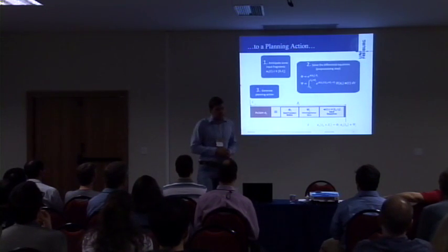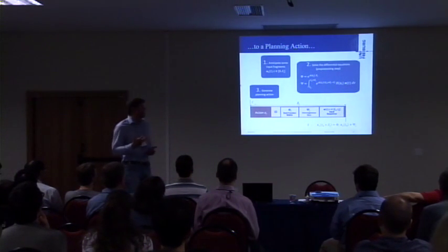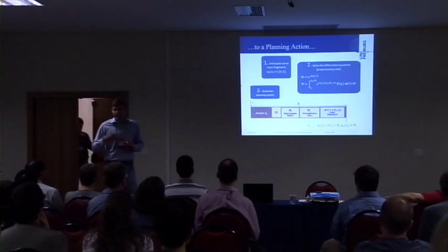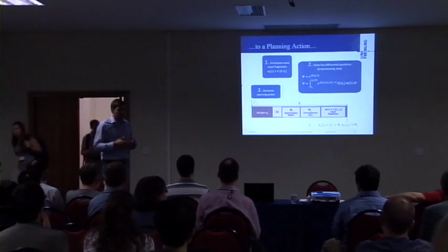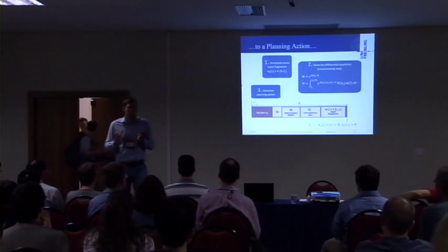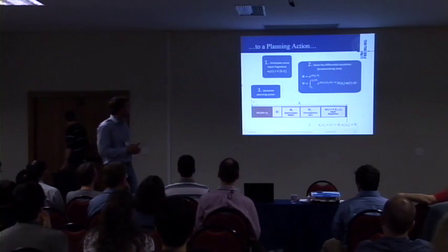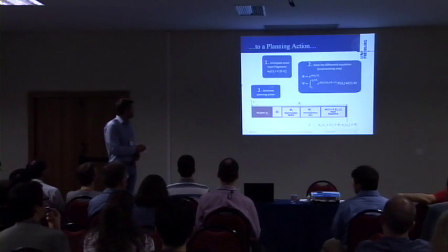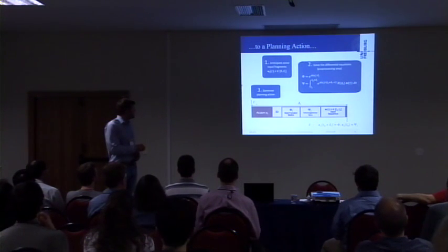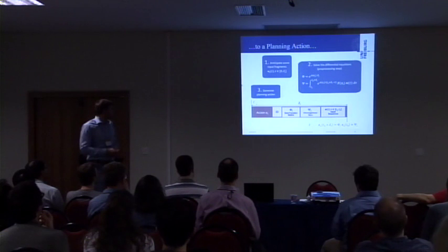Therefore, we basically have a three-step process. First of all, we anticipate some input fragments, for instance, the actuation of a thruster or a whole braking maneuver, or something that we can imagine could be useful to solve the control task. In the second step, we solve the differential equations of the hybrid system, and in the third step, we generate the planning action here, having preconditions, having a duration, and effects.